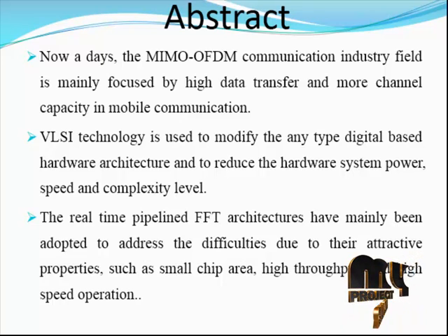Fast Fourier transform has played a significant role in the digital signal processing field, especially in advanced communication systems such as orthogonal frequency division multiplexing and asymmetric digital subscriber line. All these systems require that the FFT computation be high throughput and low latency. Therefore, designing a high performance FFT circuit is an important solution to the above mentioned problems. In particular, pipeline FFT architectures have mainly been adopted to address these difficulties due to their attractive properties such as small chip area, high throughput and low power consumption.